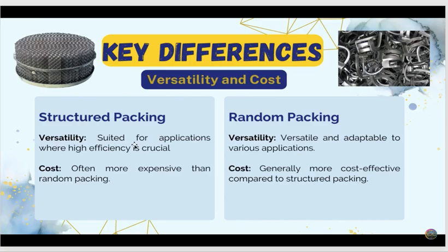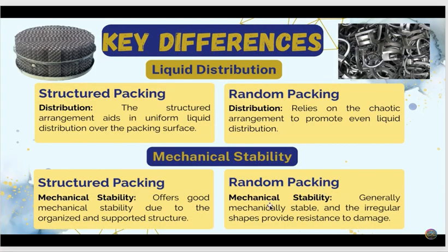Structured packing versatility: suited for applications where high efficiency is crucial, cost often more expensive. But the random packing here is versatile and adaptable to various applications, many applications in chemical processing, and generally more cost effective in comparison to structured packing. Structured packing mechanical stability: it offers good mechanical stability due to the organized and supported structure. Here, the random packing is generally mechanically stable, and the irregular shape provides resistance to damage because it is not organized.